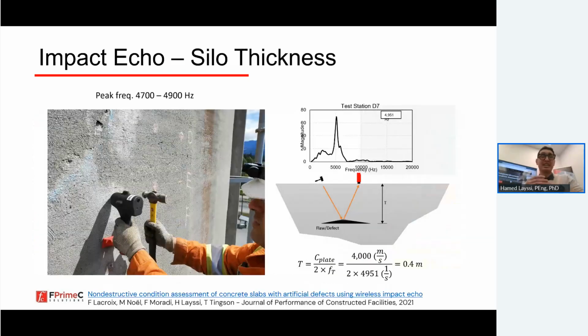And as a last stage, in order to see if the delaminated section is limited to what we visually see, and if other areas are also affected, we performed the test we call impact echo. As I said, impact echo is very sensitive to layers of delamination. Our analogy for this test was that if this is solid 400 millimeter thick concrete, the dominant peak frequency should come back at the thickness level. If we don't see that, and the peak comes at a higher frequency, it means we have a plane of separation at a shallower depth, and that might be delamination.